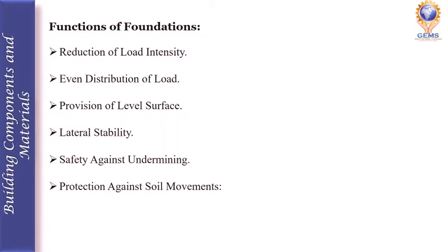If the safe bearing capacity of the soil is exceeded by the total load intensity, the structure will fail. Okay, so to reduce the total load intensity, the foundation distributes the load of the superstructure to a larger area.